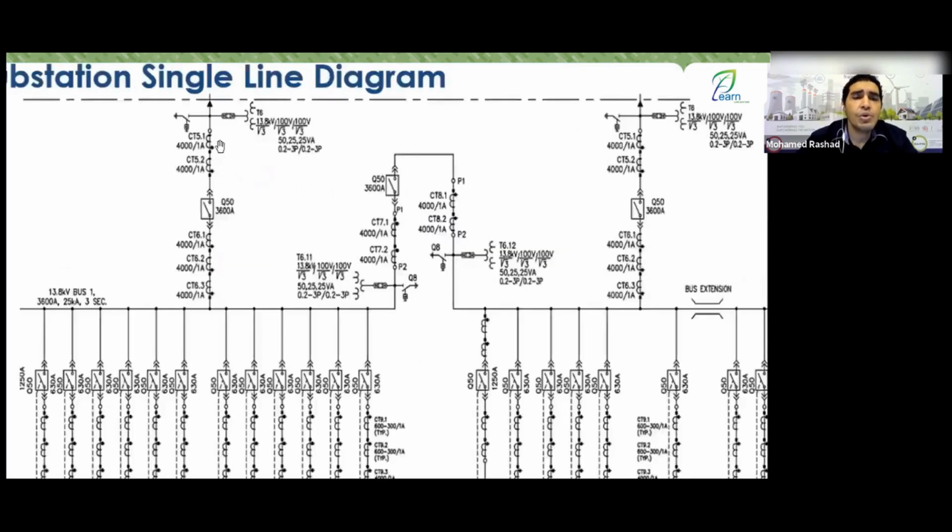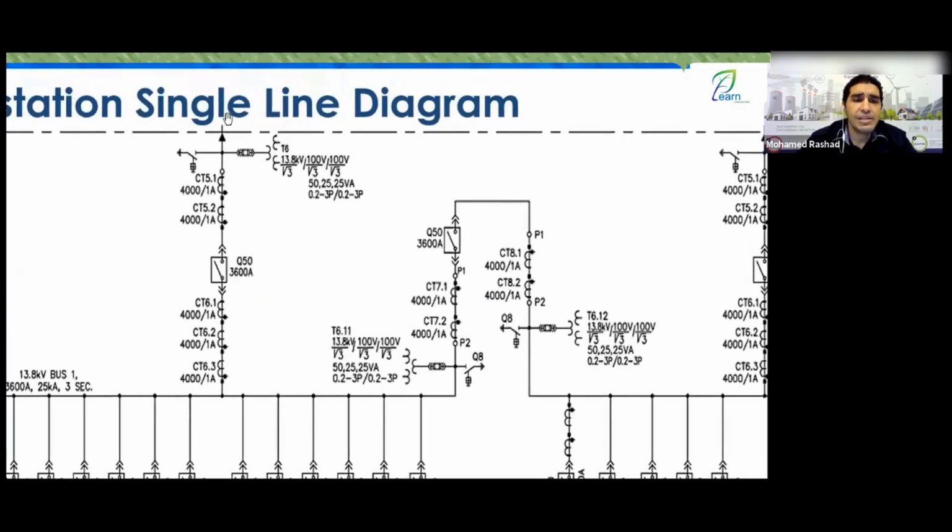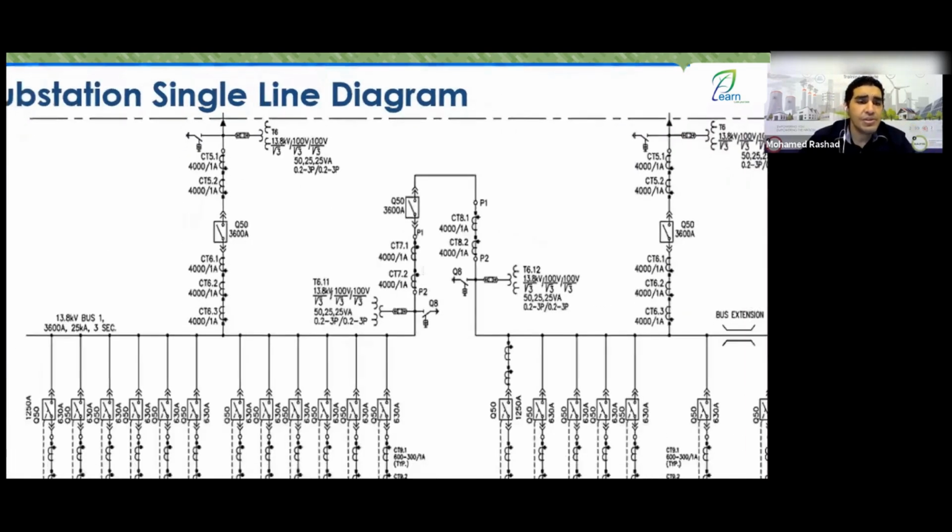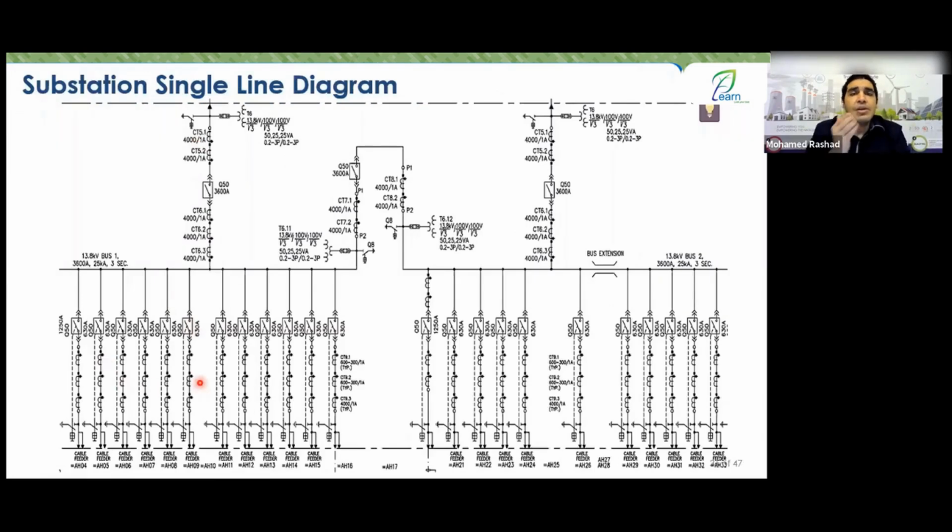Before, you will find simply that you have your cable coming to you, and of course it enters into a breaker. Before the breaker, there is the earth switch. The incomer is the same as the outgoing: single bus, single breaker, consisting of a withdrawable circuit breaker, like the diagram you see here, and with it, an earth switch, and from above here, it comes from a transformer.